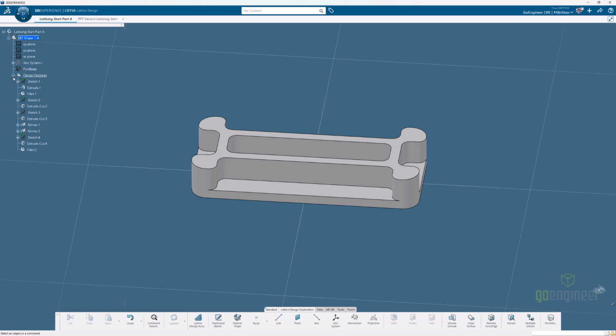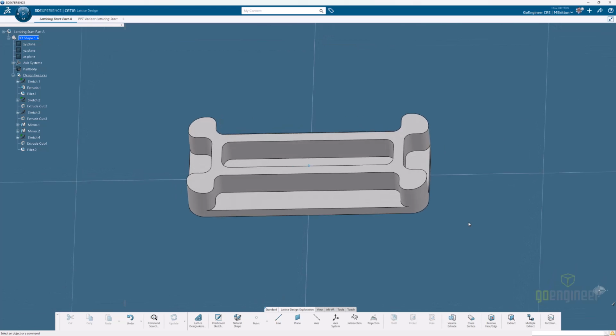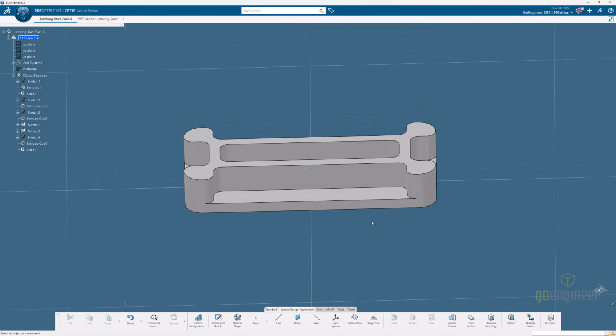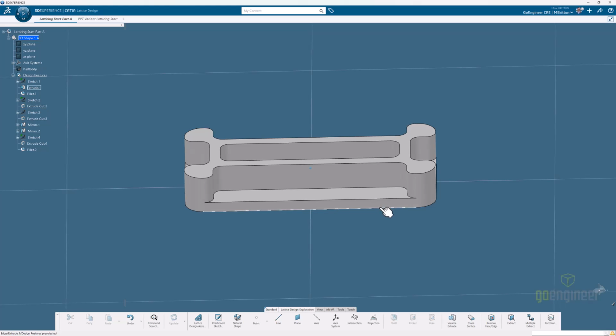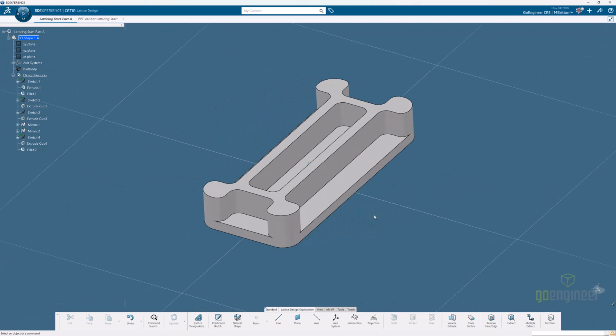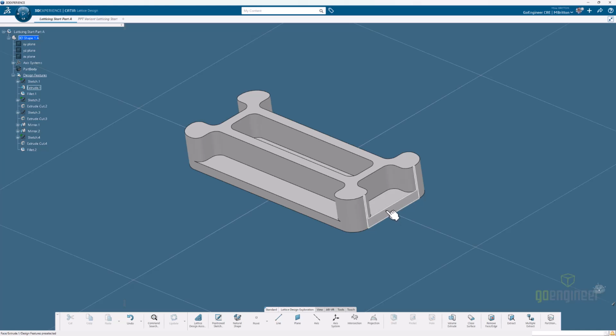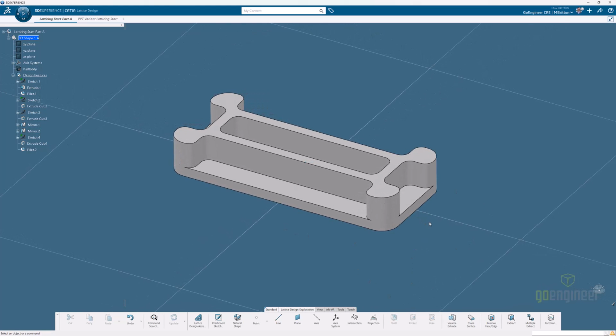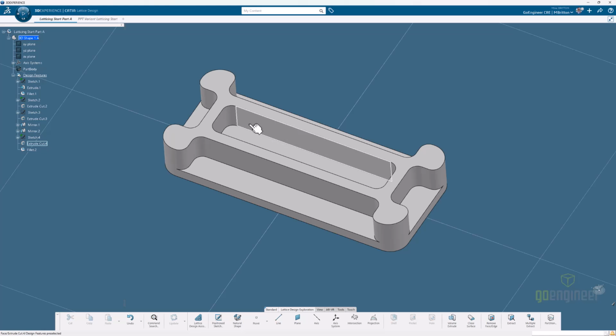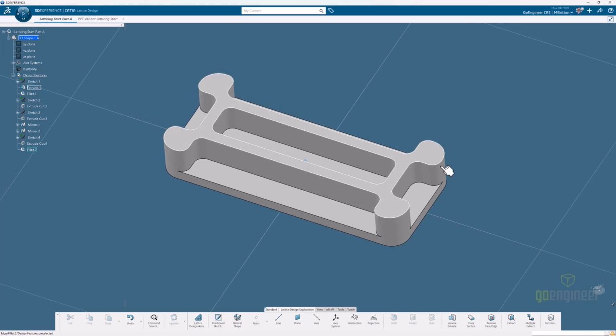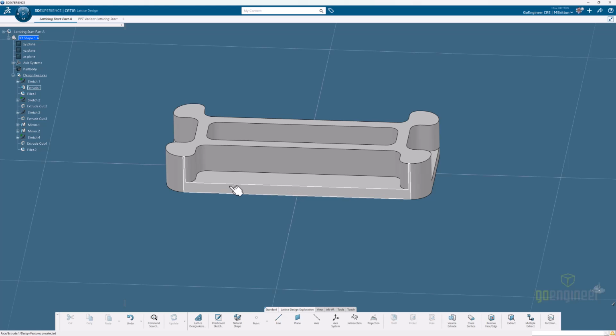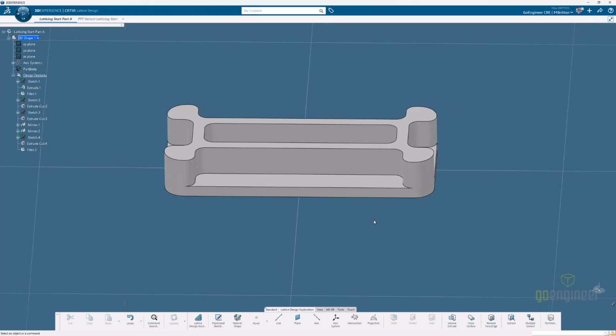As I expand this geometric set, we can see all of my features like I would in my normal design feature tree. In order to lattice, I need to define these areas and say that these volumes here, here, here are all areas that can be latticed. This interior pocket will be easily picked up by the existing features, but I need to put a partition in these other areas to make sure the software knows where to look. So let's define some of these volumes.